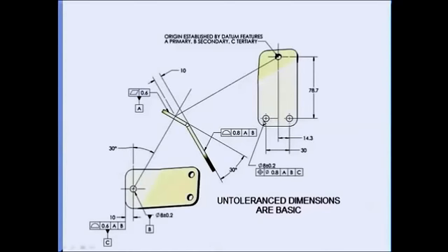So now the dimensioning becomes simpler. From my 0, 0, 0 origin, established by my datum features, I have the 78.7 dimension, and then the 14.3 and the 30 dimensions. But they're not locating a point in space, they're locating the axis. So I can then measure the holes to find out how much they've deviated from their basic location.